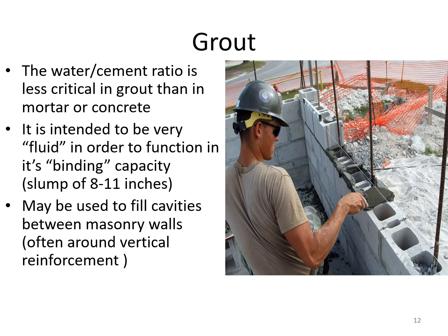Now, remember, there's a weep area, what they call. There's a void between the brick and the other type of material that makes up the walls. So let's say we have wooden construction with a plywood sheathing. Then we have a moisture barrier outside that, like a Tyvek or tar paper in the old days. Then we have a void, and then the brick is placed. The bricks are held to the wall with what are called brick ties. I used to call them a waffle type. They look almost like a crinkle chip or potato chip in that configuration. They are no longer allowed.